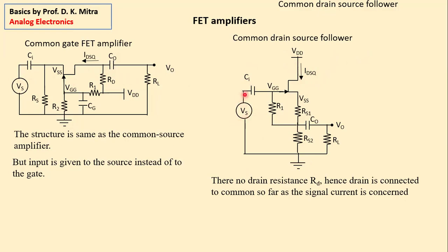When signal current flows through this, whatever very small current is concerned, and the signal potential appears here, and there is a varying signal current in this line. This varying signal current is shorted to common in this line through the DC power supply, because you remember I told a number of times any DC supply is actually a short circuit for AC supply.